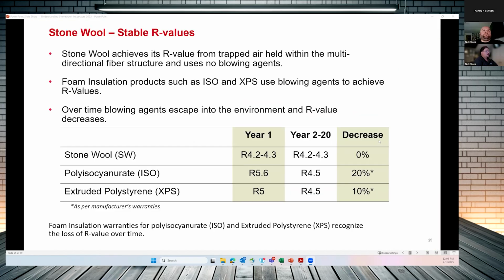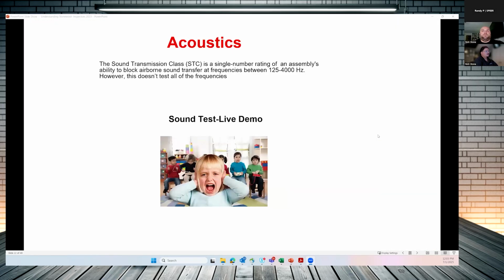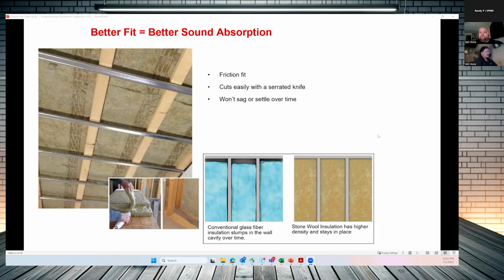And just to interject there a little bit, Nick, especially for this group, it's also important to note that as you're going into homes and testing things, if you were to take that thermal imaging camera and look at any warm spots within a wall cavity, those areas where the fiberglass has started to settle at the tops, or let's say you have an older home with a rodent issue, and you could start seeing the separation where the rodents are digging through the fiberglass in the middle of the walls.